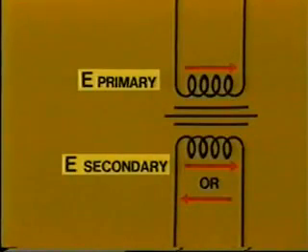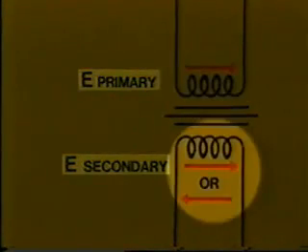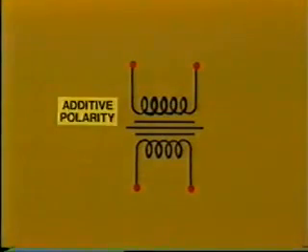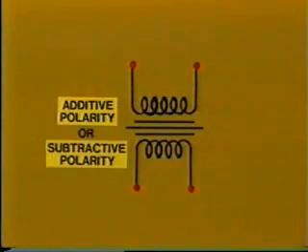This subject was briefly discussed in the previous tape on substation transformers. As you remember, polarity refers to the relative direction of primary and secondary voltages. Let us emphasize again that when connecting single-phase transformers to form a three-phase bank, or likewise when paralleling two or more transformers, it is absolutely essential that they be connected with the same polarity. Single-phase transformers are built with either additive or subtractive polarity.